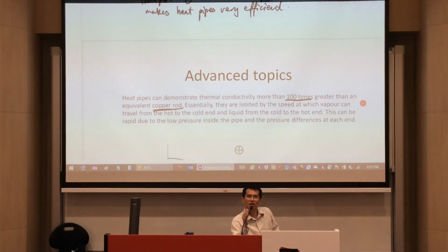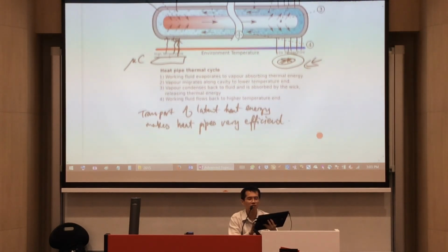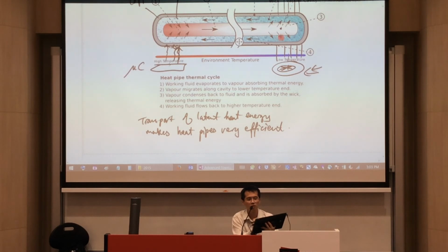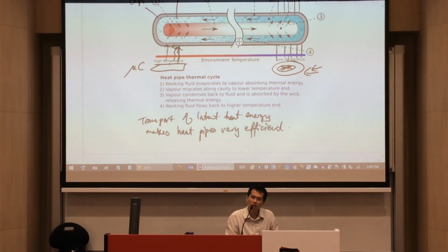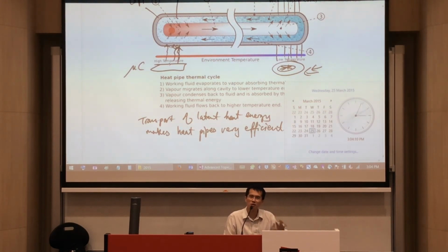This laptop that I was saying, this mechanism of heat pipe that I was saying resides in your laptop. Now, while I was saying that it's possible for this cooled down liquid, after the forced convection over here, it will cool down that alcohol vapor into the liquid state, and then you move back via the wick into this hot region again. Move back. Just now I said automatically.